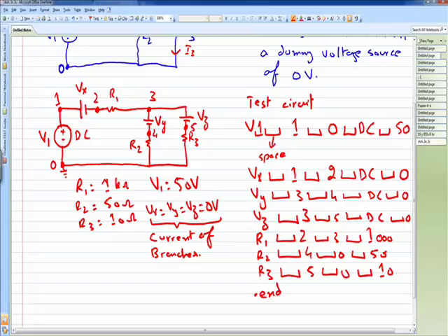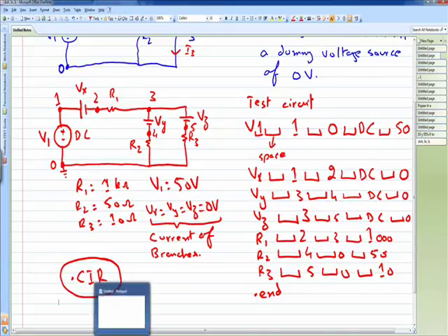So when we simulate this circuit, it will give us all the voltages at different nodes, and similarly we will get all the currents required for the R2 branch, R3 branch, and the source current. But one thing: we have to write this in a specific format, which is known as the .cir format. We will be renaming every file with this .cir format. So we will now see how we can put this circuit in a .cir format.